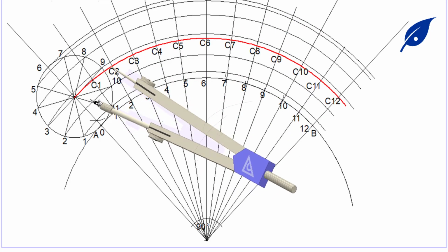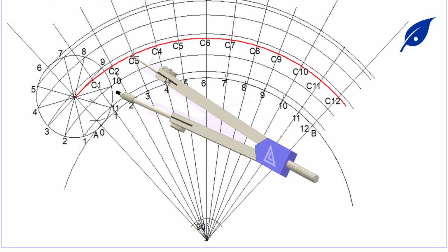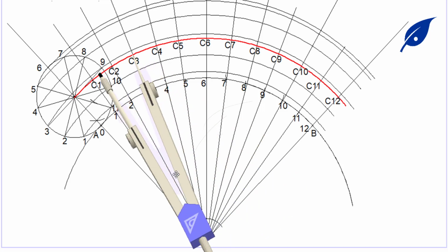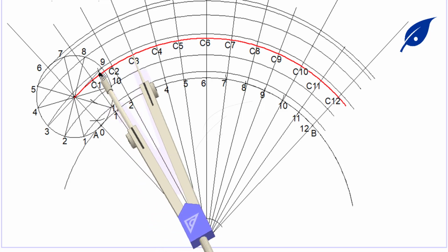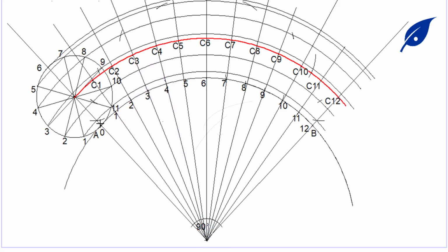Then we repeat the same process for C3 up to C12, so that we can get where the circle is touching the line as it is moving along that path outside the base circle. Now we've gotten all of our 12 points. Now start marking each of those points. I have to mark them so that I'll get my accurate required points when I'm connecting my lines.